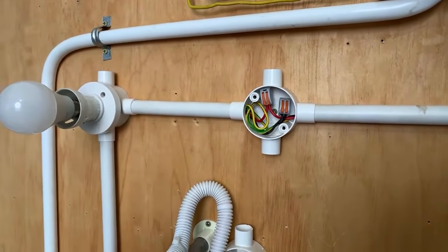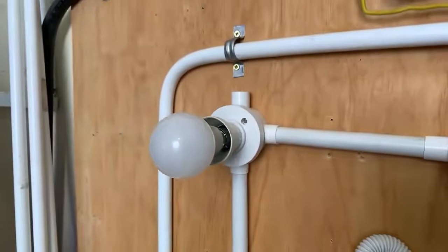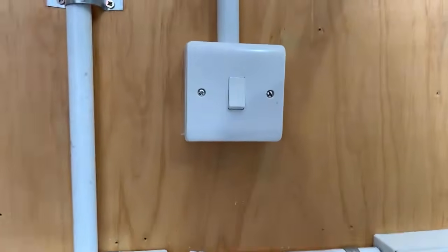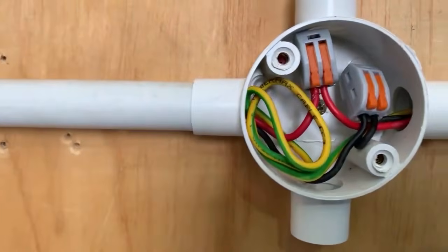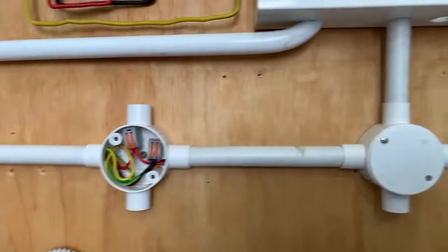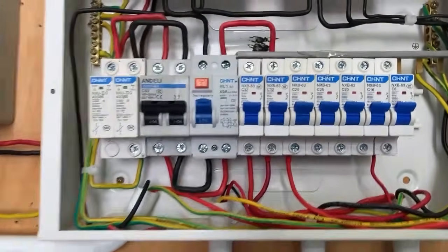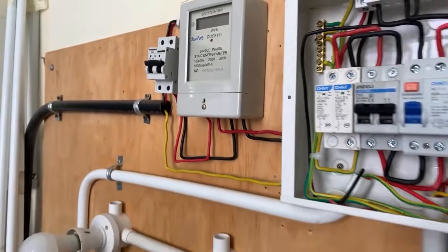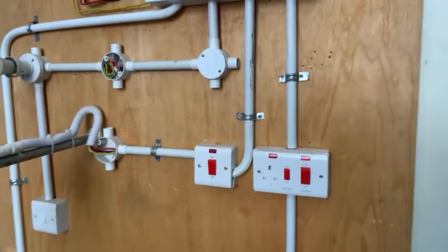But if it occurs, you find that it is in the fixtures, the bulb holders, or at the connection where you have that lighting, probably the switches, or if there's a loose connection at the JB junction box right there, or any looping or termination box, right? We're going to talk about that, especially at the meter box. If there's a loose connection, definitely you are going to have it rough.